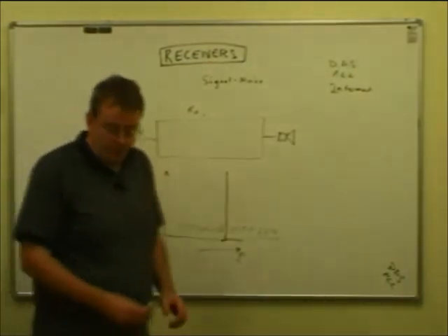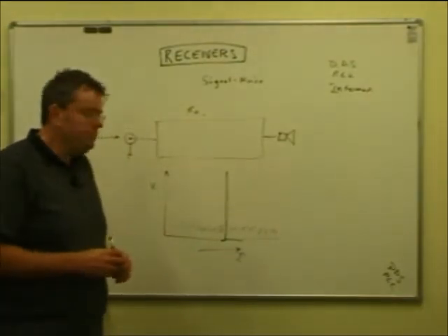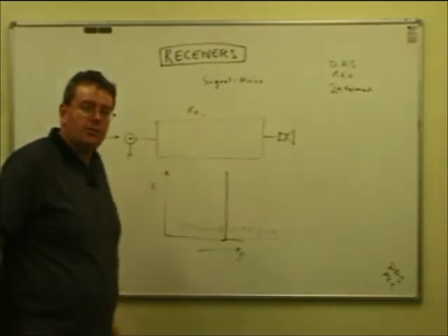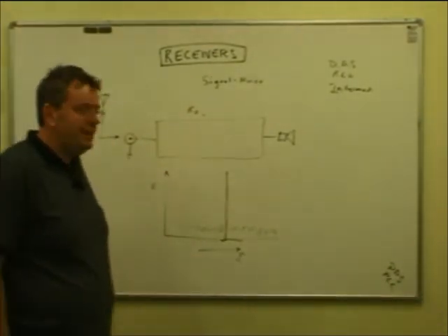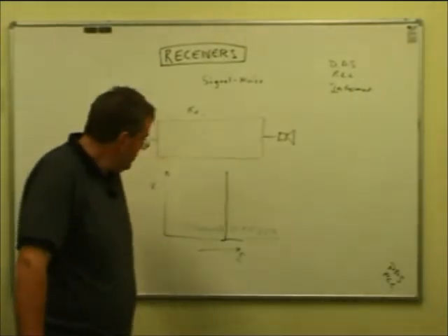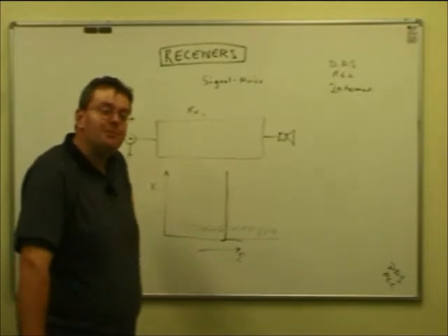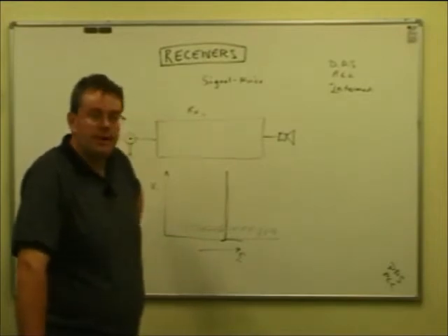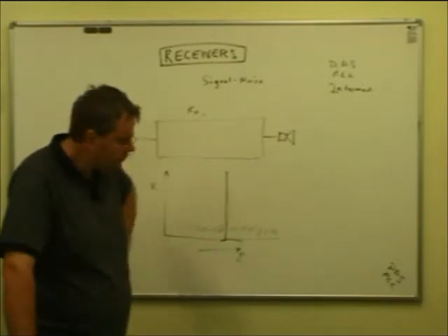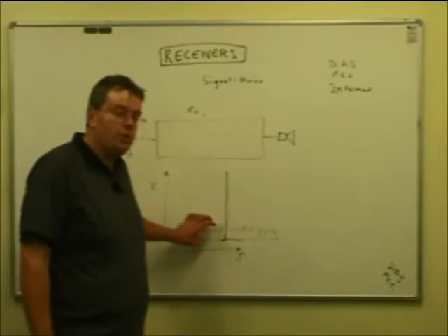Now that noise is coming from a variety of places. In the high frequency bands, there'll be quite random, sudden bursts and increases in level from lightning strikes all around the world. You'll hear as static what's called static crashes. There'll be some man-made noise and other stuff, and on some of the high frequency bands a bit higher up you'll get noise from outer space. Jupiter adds its share around the 15-metre band and all sorts of things. So that's contributing to the background rubbish that we don't want to hear, the noise.